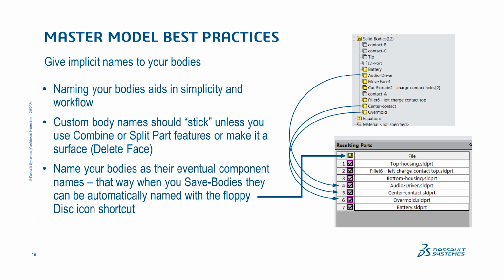Yeah, so I mentioned this before with save bodies, and it's the reason that's probably my preferred master model technique: if things do go wrong, you have a way out with save bodies, because you're able to edit from the derived part the body that should be correctly assigned to that derived part.